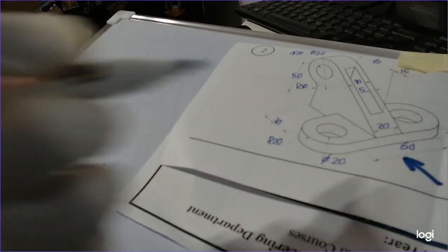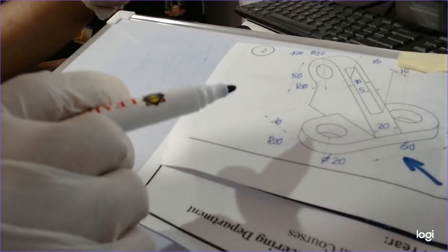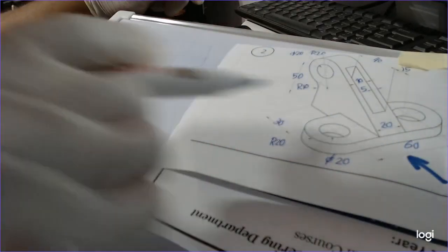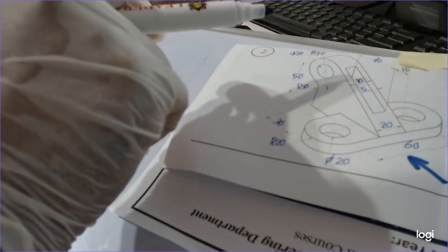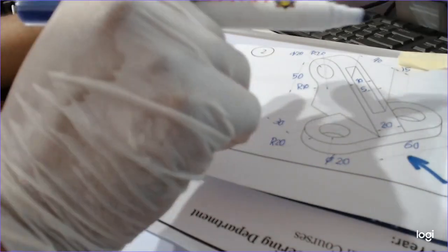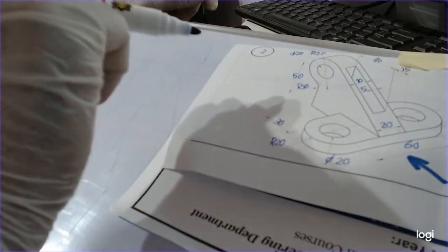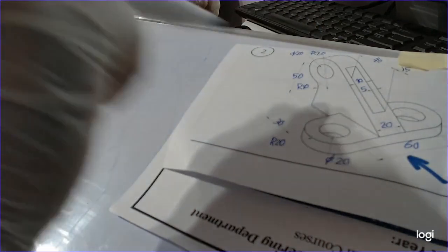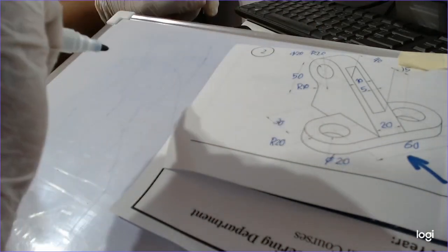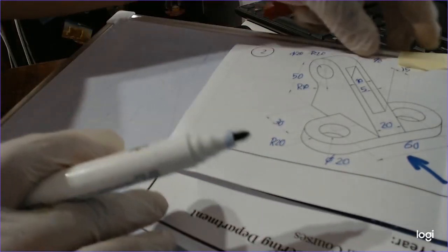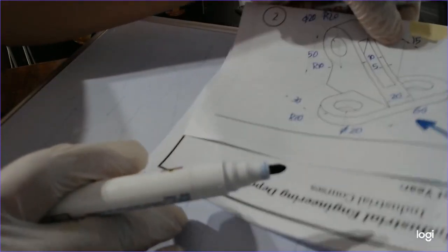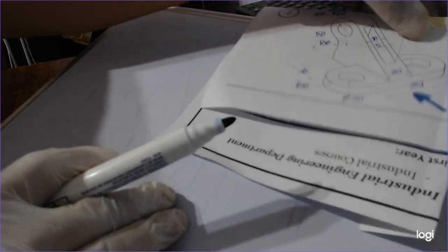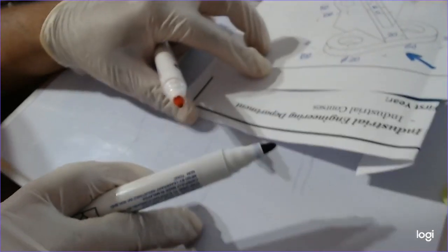So if we draw this view on the separate sheet, we'll draw it on the right side, because actually this one is a symmetrical object. That means that we can draw either the right side view or the left side view. But actually we have the open one is the left side view, so we can proceed with the left side view of this object. Okay, so for the front view, actually this slot shape would be something like a rectangle. So let's do it here.